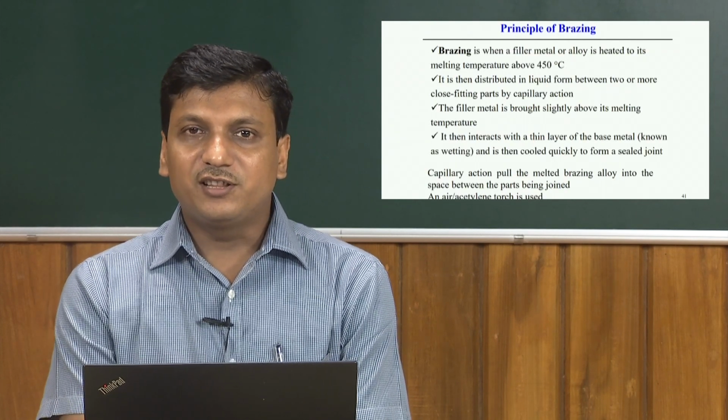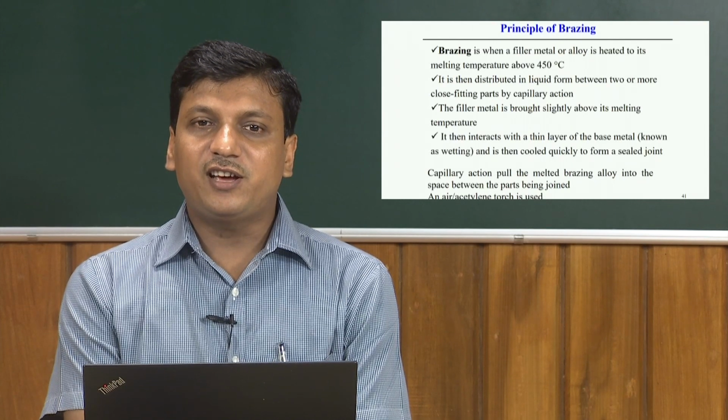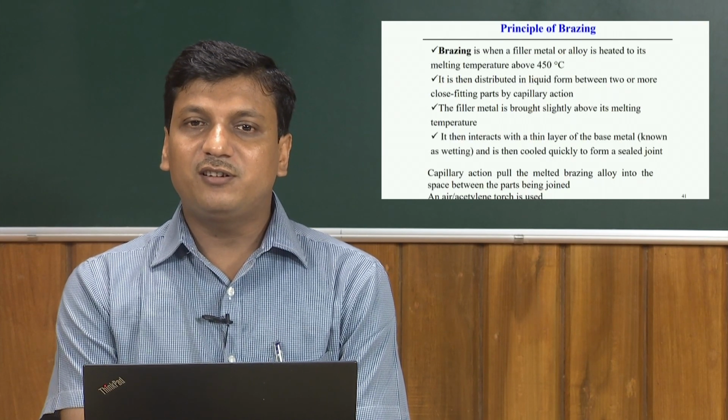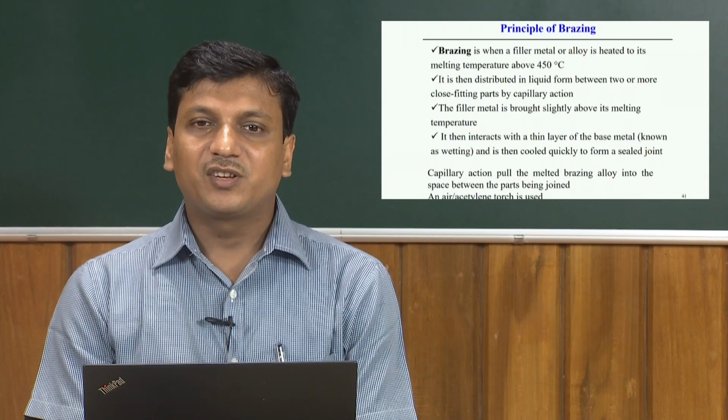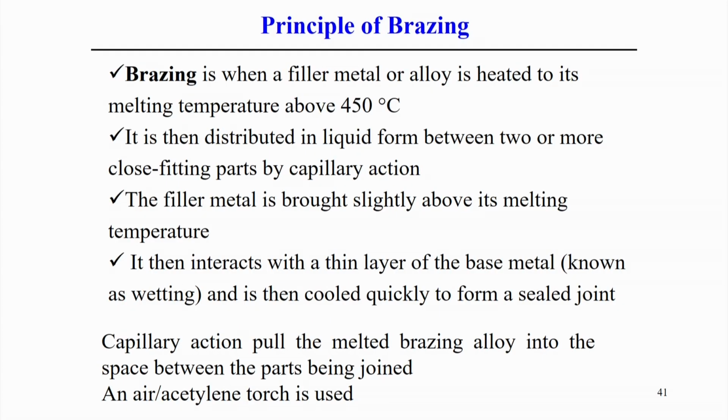So, definitely the main principle is the capillary action of the liquid metal, meaning the brazing alloy that fills the gap between the parts to be joined. So, on that principle the brazing process works. In this case, to melt the brazing alloy or filler material, it is necessary to apply some source of heat.